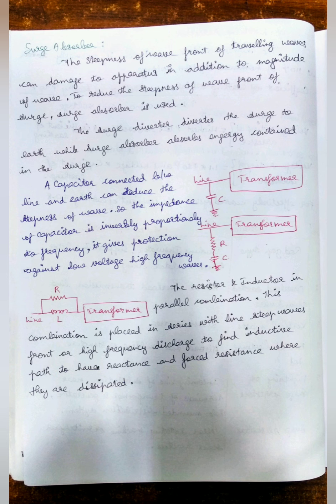Next, the surge arrester and surge absorber. Normally the arrester is commonly known as a diverter, which means it diverts the over voltage from a line to the ground for a particular time. After that, it gets back into a normal condition. If the condition is exaggerated, or the time where the conduction takes place is at a higher level, the LA gets blasted, or even a ground fault will occur.